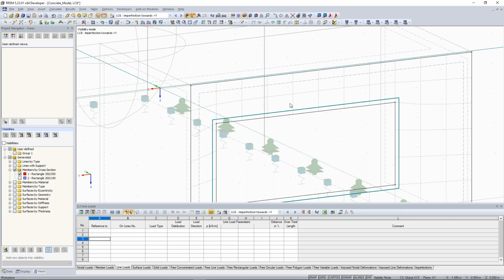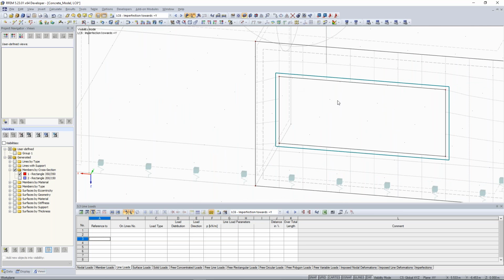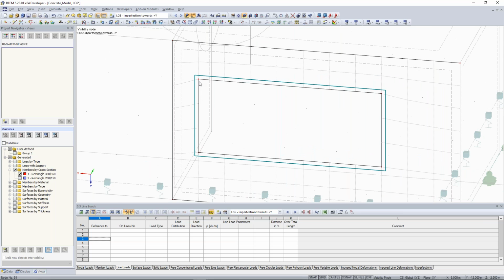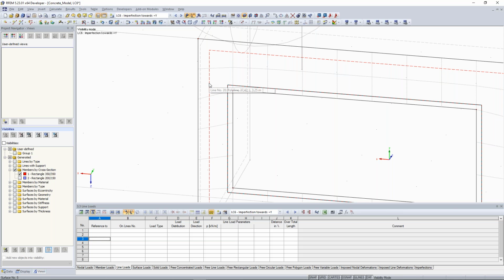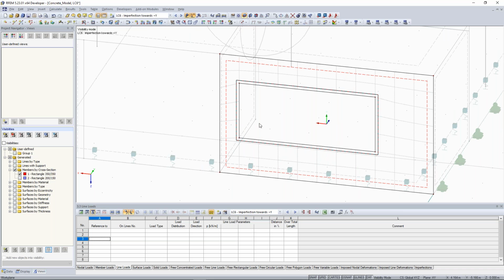Again, here at the corners, you will probably get singularities, because here you have just one FE element, and along one FE element the results are calculated. I don't know if you get good results here. So my recommendation would be that you do some FE mesh refinements here.